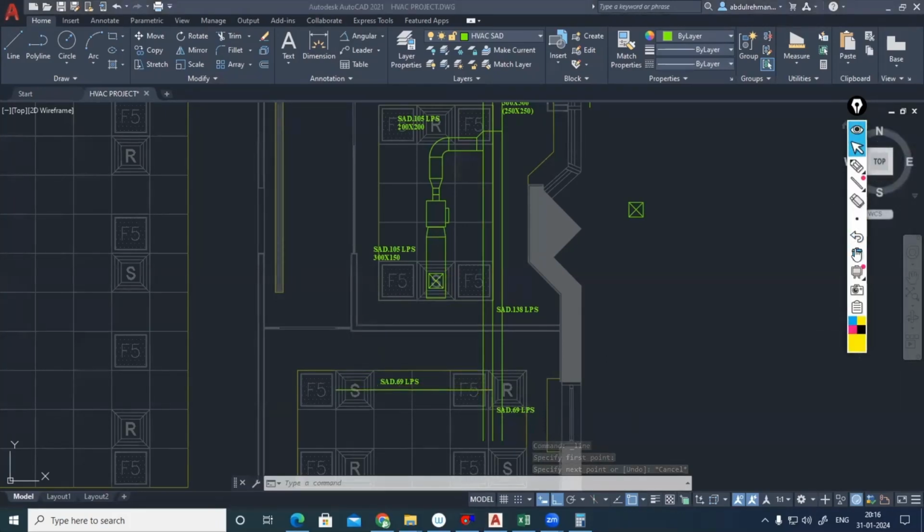And also if you are using 200 dia flexible duct, because if you want to take a 200 dia flexible duct from this side, this height should be 250 mm minimum. Then only I can take it. Already this is 250 only, we are getting it. There is one problem. But if you are not using this flexible duct, because from the starting, from this point to this point, it is not possible to take the flexible duct.